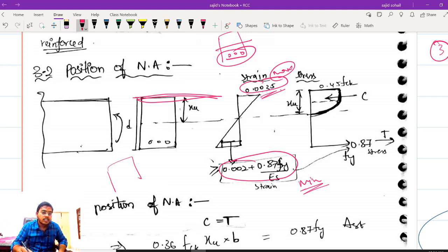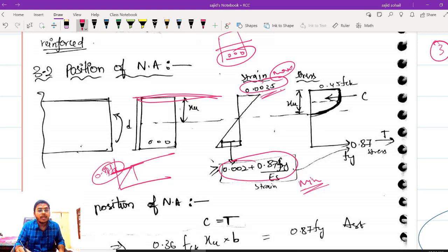If you are constructing some structure, it will extend and give deflection up to some extent. But obviously we have our limits of serviceability also, right? Deflection should not be too much, so we are not taking that much. We never calculate maximum strain in steel. Always it is minimum strain, to be on the safe side. If you are applying this minimum strain, you will be reaching the maximum stress of 0.87 fy. That means if you are reaching this much strain, the entire steel is using its maximum capacity. Every inch of your steel is properly being utilized.